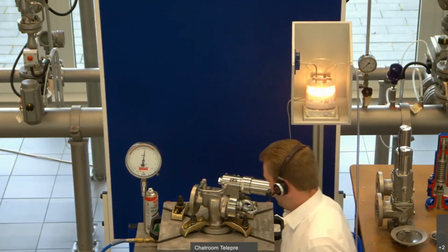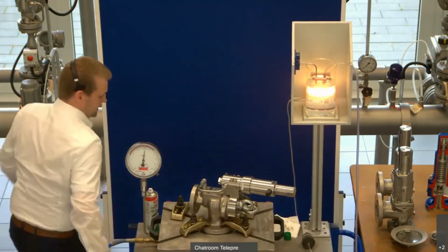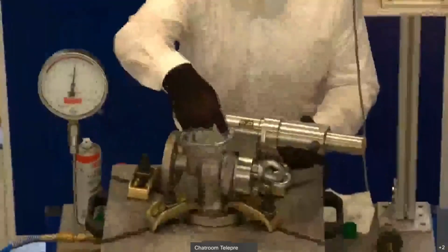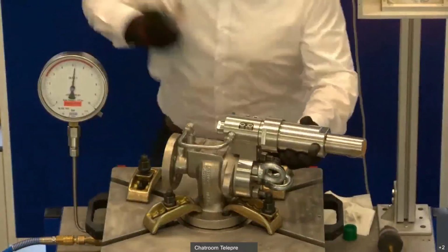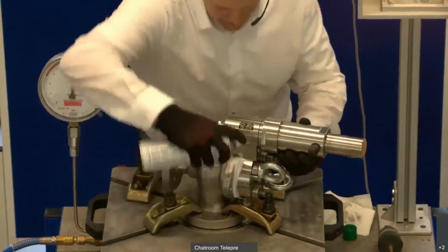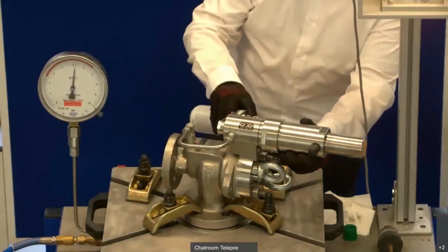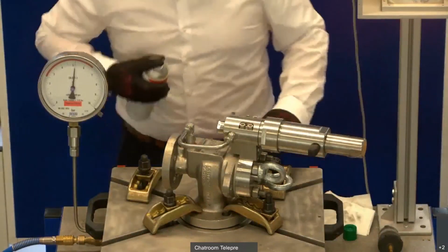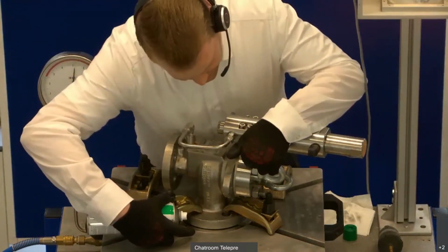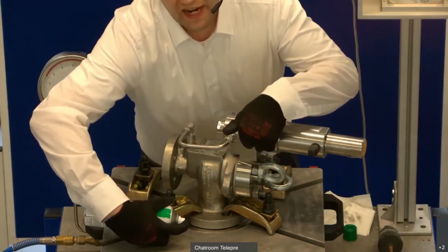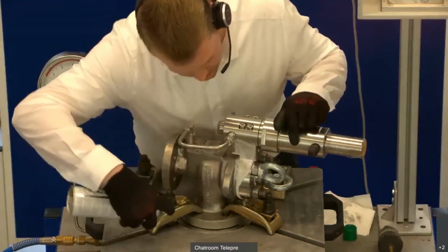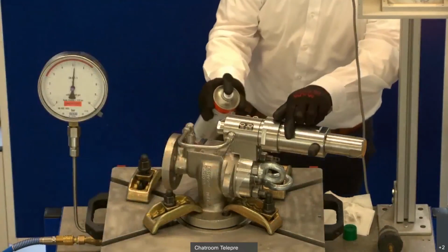And now we have to do some other parts. Here you see now we have the top plate, a connection to the body. This is to spray with our liquid spray and look if there are some bubbles or not. From my side, the same. We see no bubbles, and there is a connection from the top plate to the pilot here. We have to spray it again on this connection. See, there are no bubbles. From my side, the same.